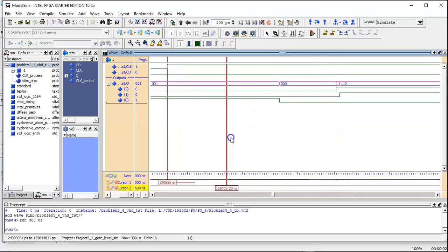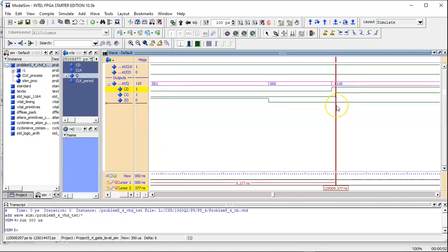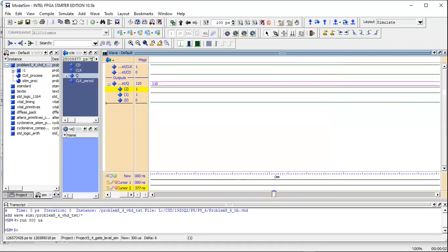This is the initial code 0, 0, 1, and then what is expected is 1, 1, 0. But in between these two codes you have the code 0, 0, 0, and then even this one here, which is the 1, 0, 0, right? So this is what happens in these systems, and you can watch this thing here in this gate level simulation.